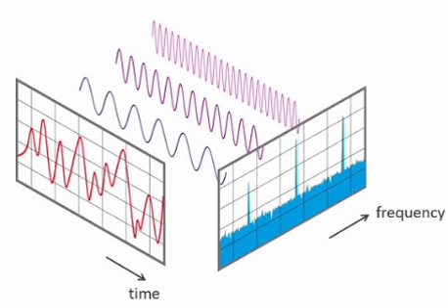Linearity: a x1 of s plus b x2 of s, ROC is R1 intersection R2. Remember, R1 intersection R2. Time shifting: x of t minus t naught gives e power minus s t naught X of s, and the ROC is only R. Shifting in the s domain: e power s naught t x of t gives X of s minus s naught, then the ROC is a shifted version of R.